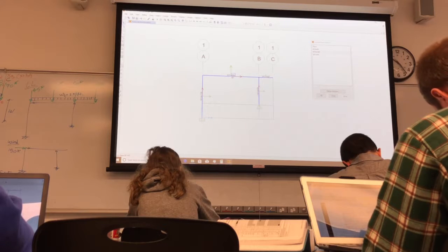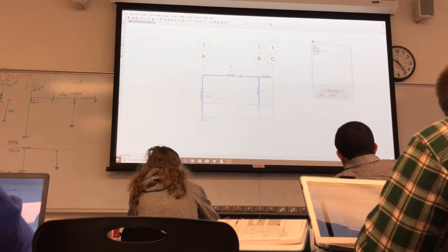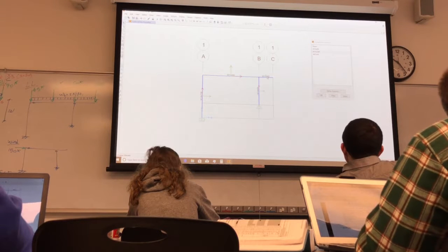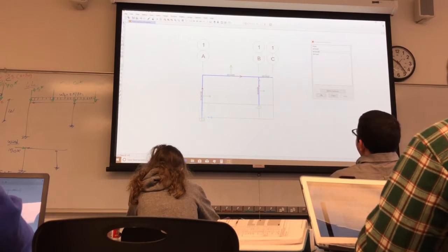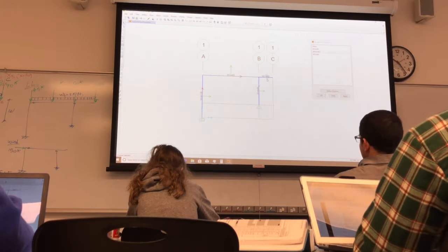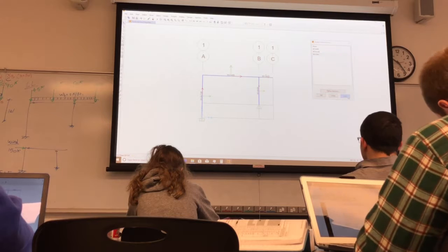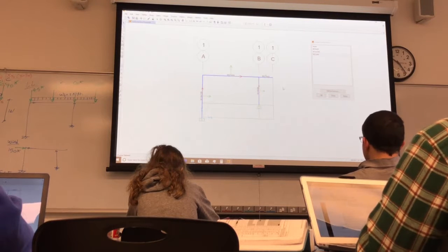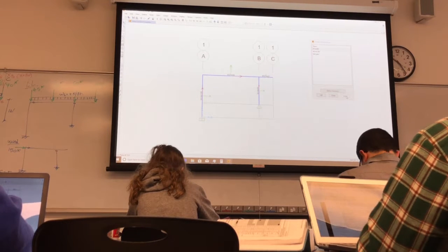And then the beam, as you can see, SAP assigned everything as the first section you assigned. So you need to change that. And then the beam, we have two beam elements, right? We said we have to have two beam elements. Otherwise, SAP will not understand that there's a connection. So we need to select these two and click on the W21 by 44. That's it. And this one is already assigned as a 14 by 99. So we're good. So we assigned the sections.